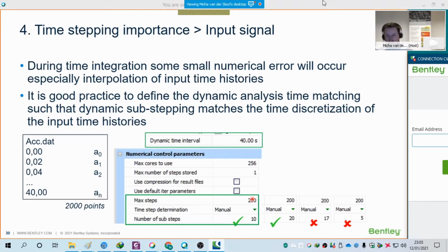It will also generate a lot of data on your computer. Plus the max steps that we have is limited here to 10,000. So if you have more than 10,000 data points, it will not fit in having this as 10,000. So then you also have to use the number of substeps. So it's also a matter of data points which are completely stored and can lead to a lot of data, especially when doing dynamics in, for instance, 3D, then the data can be so much that you really have to take that into account, getting hundreds of gigabytes of data on your computer. So that's also something to consider while choosing this. If you just store everything, it will generate a lot of data.